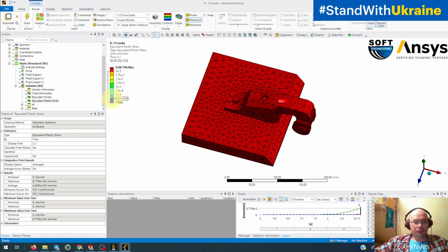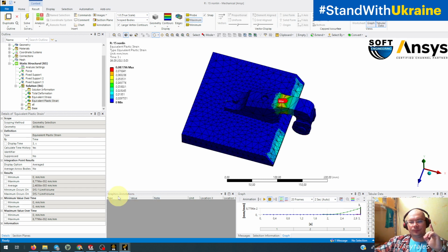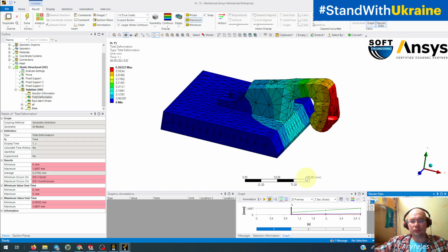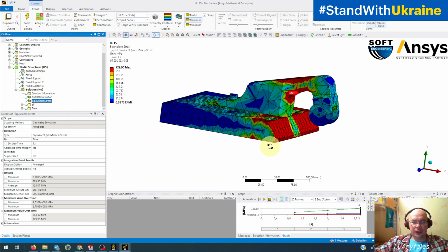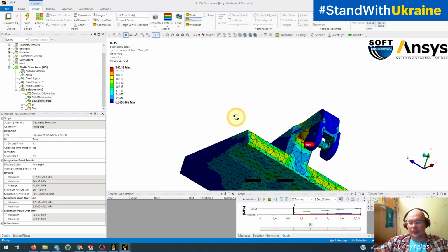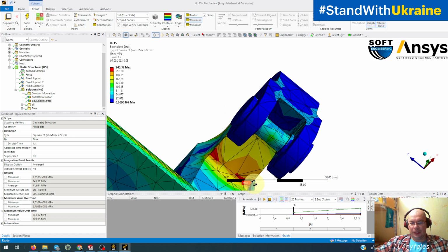100 times less stiffness, but with some percent of plastic behavior. Okay, we understand that. But there is one additional thing that we need to explain. If we return here to our 1 second, to 1000 newtons of load, and take a look at this result, sorry, and here we must return, we'll see that we have 243 megapascals of stress in those places.